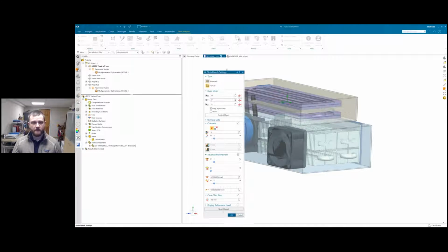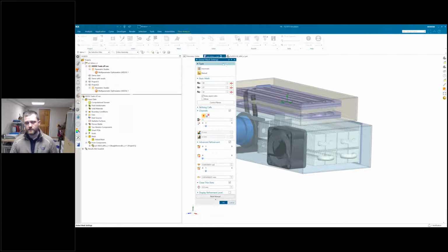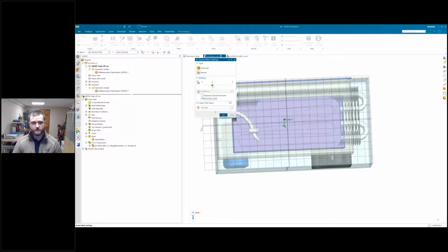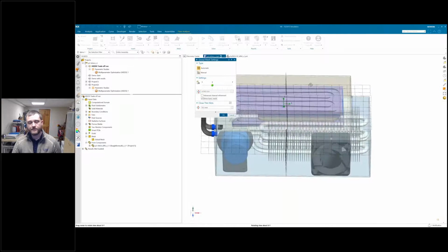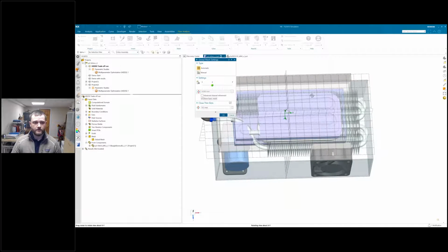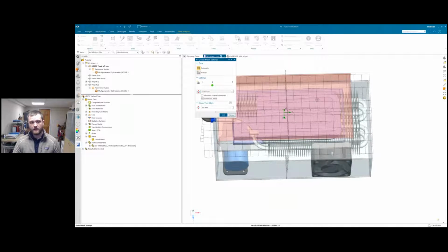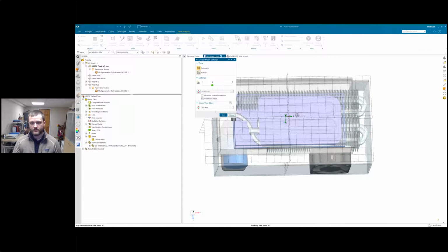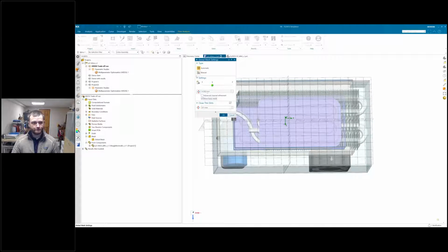As I said, we can do refined local meshes too, but in this case, we're just using a large global mesh that has some automatic refinements in it. And I'll just switch over to the automatic. So you can see if I show the basic mesh here, we can start with multiple values of an initial mesh. In this case, we're starting with an initial value of 3. And FlowEFD has the ability, based on passage size, curvature, things like that, to resolve the mesh at 9 levels below that. So when I say levels, a level of 2 below this would subdivide this cell into 4 cells, and so on and so forth. And we'll take a look at that here in a second.